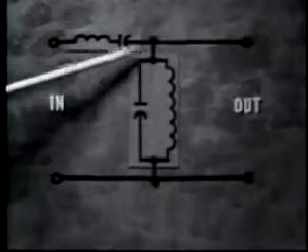The pi section band-pass filter can be constructed by, again, maintaining total circuit inductance and capacitance values the same as in this basic L section. We'll add an additional shunt leg to the basic L section like this. We now have two capacitors in parallel, so each capacitor must equal half the original capacitance. One half here and one half here.